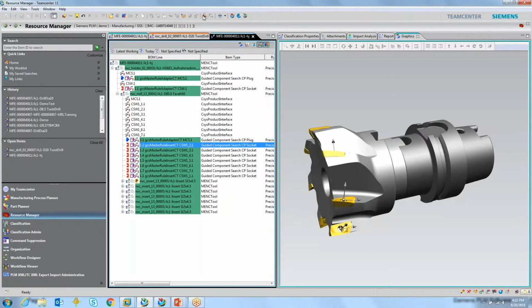And then what you would do is use this little icon. I'm going to save it. There's an icon up here. It's already made for me, so it's not showing it, but it says Create Update NX Tool Assembly. And that's all you have to do, and it creates this assembly for us. It goes in and does the spun outline. Here we go. It's highlighted up for me. It should give me a dialog box of what it's asking me to do.